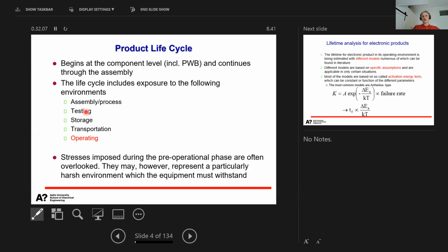The operating temperatures might go quite close to 200 nowadays when you include the environmental temperature as well as the power losses, so internal stresses, but still not up to 250. It might sound like quite a small difference, 200 versus 250, but at least for some materials, it's really critical. For example, our organic materials, our printed wiring boards, molding compounds, and these, we will come back to this issue again later on, how their material properties change as a function of temperature.